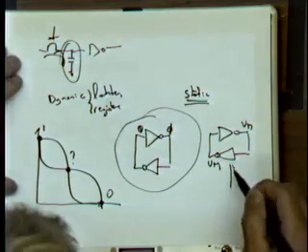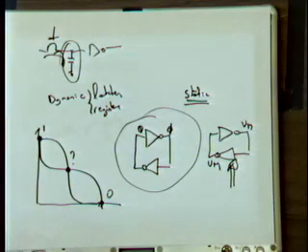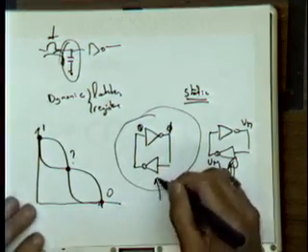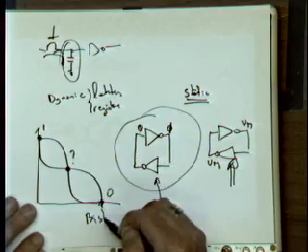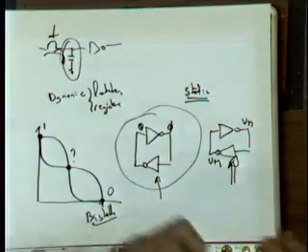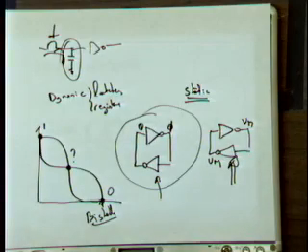The nice thing about this is that it is called metastable. It's not a stable operation point. A single electron coming by will switch this out of this position and move it either to a 1 position or a 0 position. So in reality, this is a bistable element. It's either a 1 position or a 0 position, and it will remember it. We'll come back to that in the beginning of the next lecture.